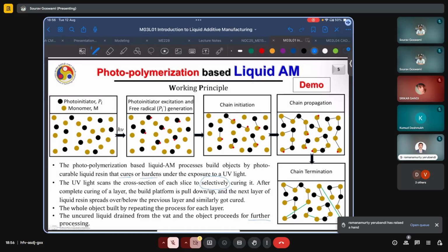The reason being that at this stage, we break off all the supports, then we put it into a UV chamber, where there is a floodlight of ultraviolet light of a wavelength relevant to the resin that you are using, and that part is left in that chamber for a suitable amount of time, and that is where the part gets fully cured, and then it becomes strong enough and it can be put to use.